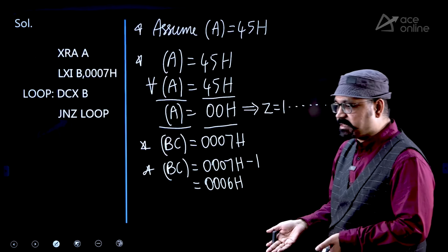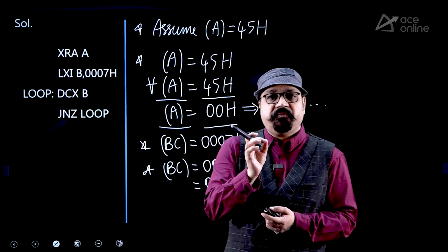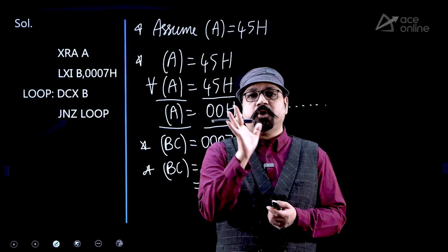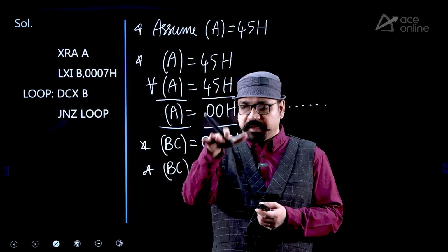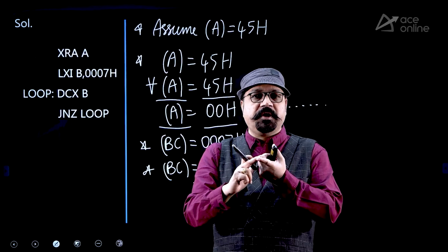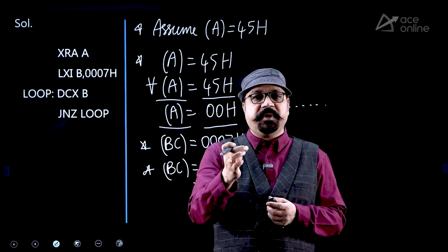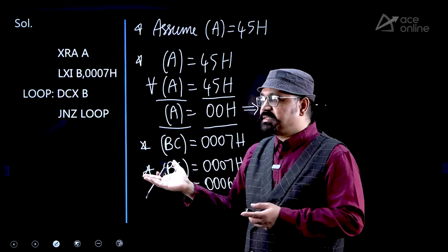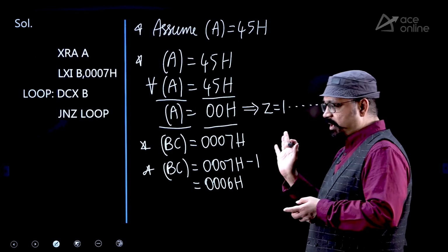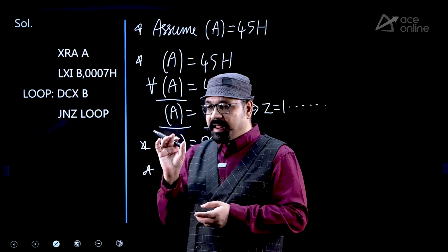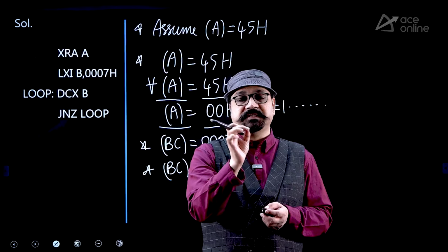This is the 8085 processor. This is a kind of special instruction. The 8085 ALU is an 8-bit ALU. It can do 8-bit operations. It can increment an 8-bit number, decrement an 8-bit number. It can add two 8-bit numbers. It can subtract, as you have just now seen, one 8-bit number from another 8-bit number. These DCX, INX operations are not done by the 8-bit ALU. They are done by a special circuit, that is the incrementer/decrementer.